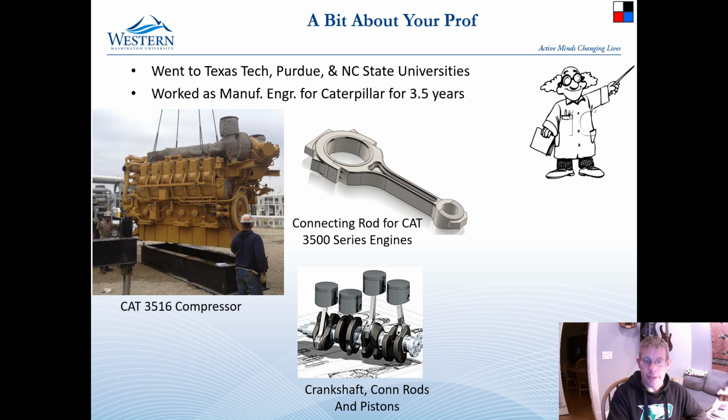It is the most highly stressed member of these engines, because when these engines were originally designed, they were producing half the horsepower that they are today, and the connecting rod has not been allowed to grow any bigger because of the space that it has inside the engine, and a couple of design constraints that they have put on this engine for its entire life. So I got to do a lot of really cool things when I was there.